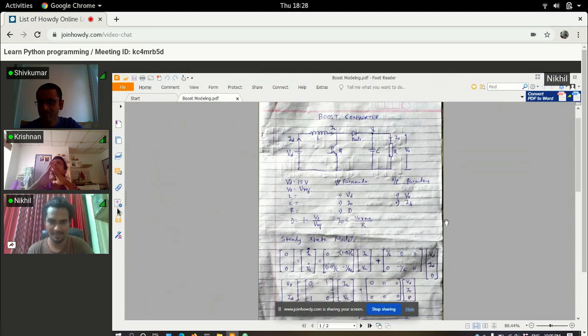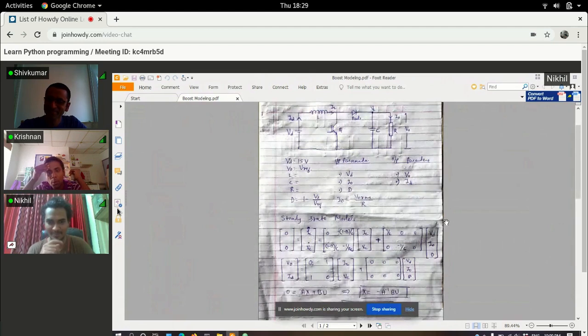Yeah, I think I was getting some error which they were highlighting on rank. I don't know about the rank, but at the end, it will not be the minimal model. Exactly. So you will end up having states dependent on each other, and if you are going to analyze properties of the system with this model, for instance, in a transfer function scenario, you will have pole zero cancellations.